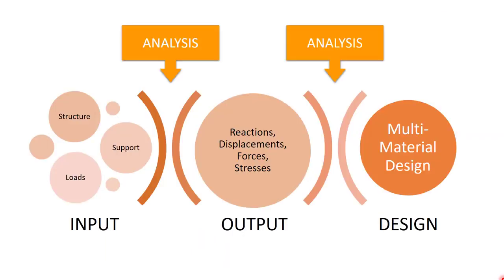You need to have an understanding of the inputs, that is, creating the model itself, defining the member geometry, defining the support of the structure, and defining the various load it bears. You need to have an understanding of the outputs. Just a mere look at the outputs and you should know whether you have dialed in the right inputs. And finally, you need to have an understanding of how the design works. A simple look at the STAAD design and you should know whether you have the right values or not.